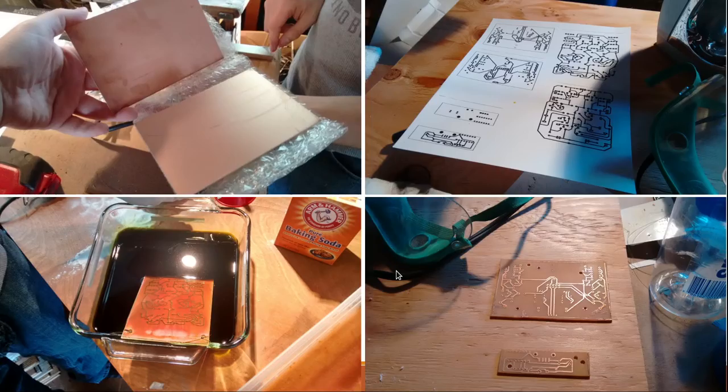The power board and main board I made starting with a blank copper board. You take photo paper and print the PCB traces on a laser printer, and the toner will not fully soak into the paper, so you can transfer it onto the copper using heat. So about 10 minutes on an iron and the toner is transferred to the copper. Then you dip that in PCB etching solution, which is an acid that eats away the copper, but the toner protects the traces, so when you're done and clean it all off, you're left with just the copper traces. And so once you drill the holes, your PCBs are complete.